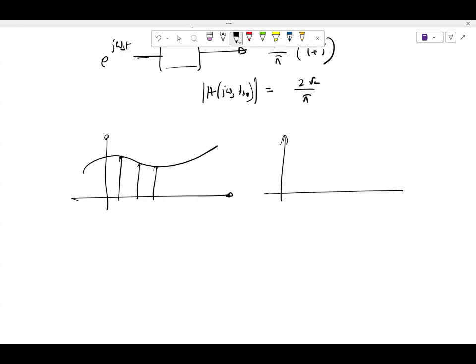I get a train of impulses weighted by the value of the signal wherever it was sampled, right? And then what if I tell you that in the time domain, I am looking at this signal and holding that value for that period till the next sampling happens? Right? So essentially in the time domain, it should look like this.